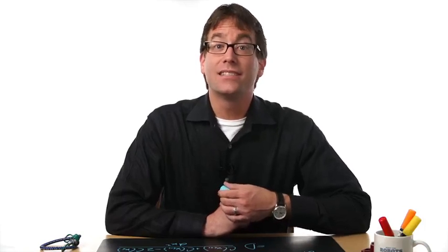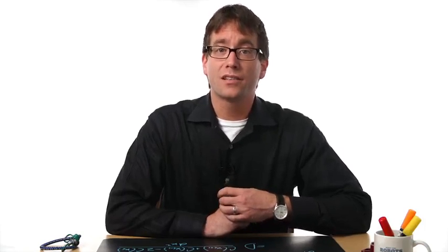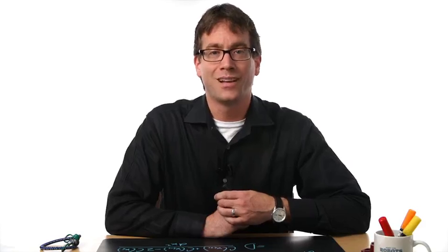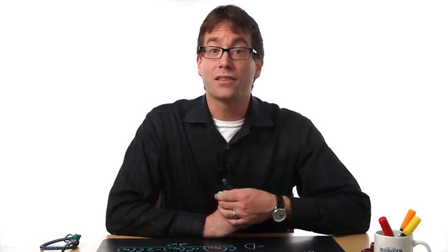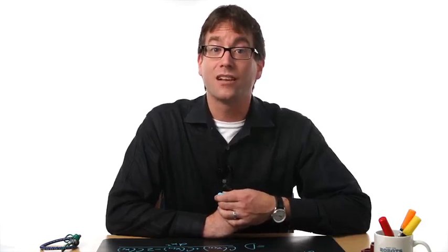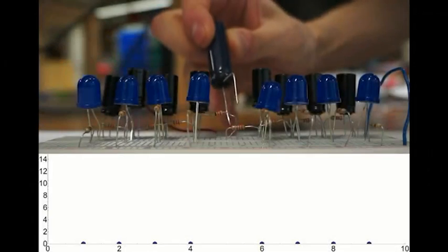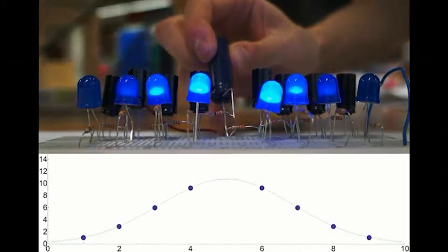Let's test this out and simulate the electrical system while plotting the solution to the diffusion equation on top of it. We can choose a total of n equals 100 capacitors, and R equals 0.1, and C equals 2. Moreover, we can choose the initial charge on every capacitor to be 0, except the one in the very middle, which we choose to have a positive initial charge of 1 coulomb. We plot the height of each state and watch it change over time, and we plot the solution to the diffusion equation on top of it. Amazingly, these two solutions are right on top of each other.